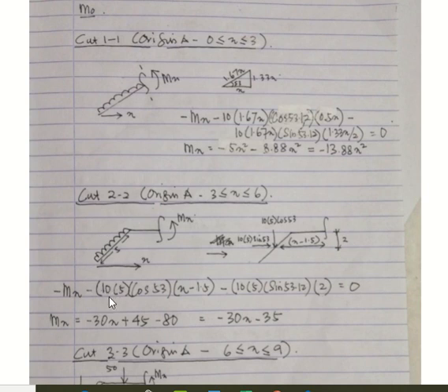That's why, for this calculation, when you want to consider this UDL, 10 multiplied by 5, because you consider the whole length. After 10 multiplied by 5, you have an imaginary line here. It looks like a point load at the midspan.